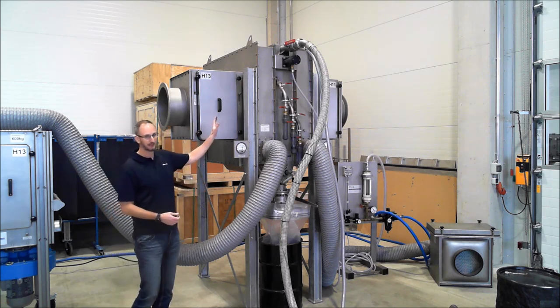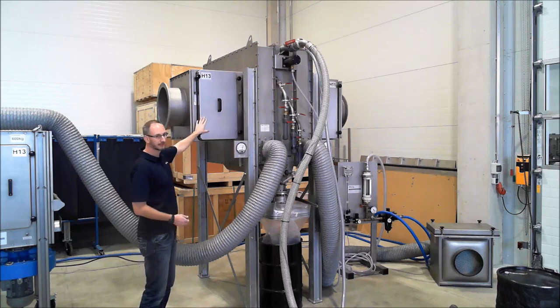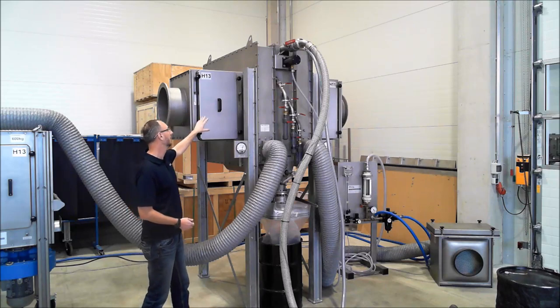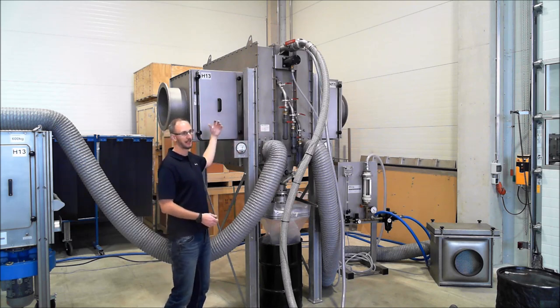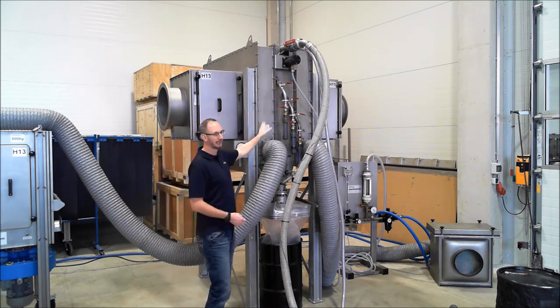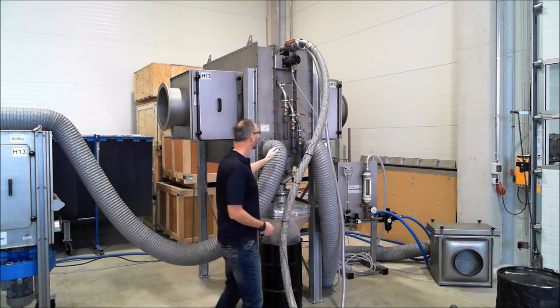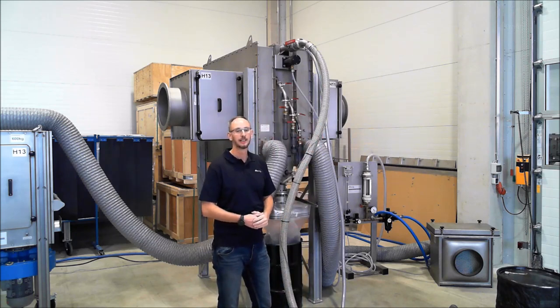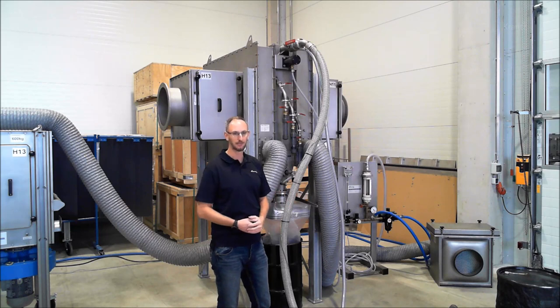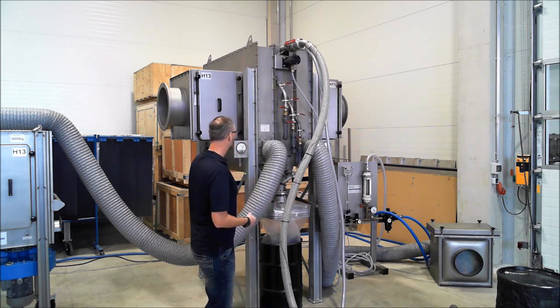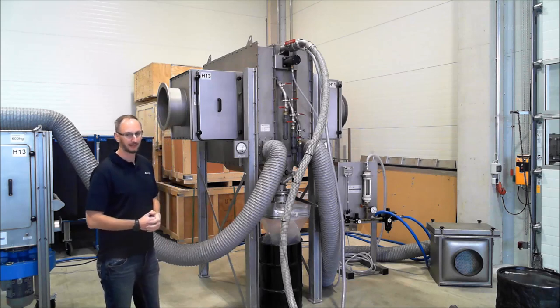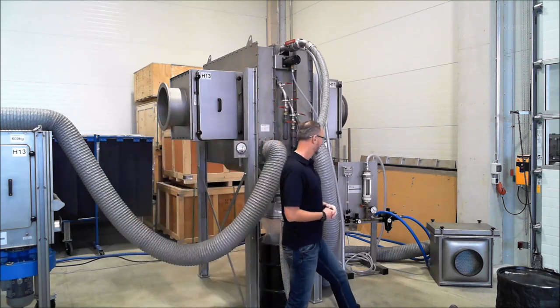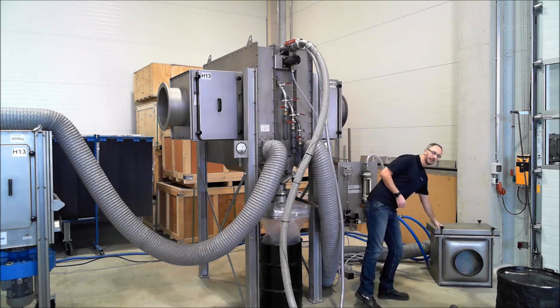We have here the carbon filtration system coming with the air inlet, pre-filtration, H13, to protect the carbon itself, so that particles will be absorbed upfront and only gases get to the carbon filtration side. On the downstream side, you see the second HEPA filter, which is the H11 filter element. This is to protect the ductwork downstream if fractions get loose from the dust, from the carbon. So this dust will be collected by this filter. To fill the carbon, we have now connected different devices. Starting on the left-hand side, we have here the air inlet filter.